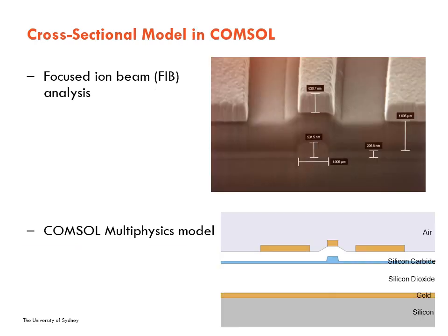For my research, I optimized the cross-sectional geometry of the electro-optic modulator fabricated earlier this year. Geometric measurements were taken using focused ion beam analysis shown above. I modeled this cross-section using COMSOL Multiphysics shown below, and analyzed its performance using the finite element method. Modal analysis allowed the group velocities and losses of the optical carrier, as well as the modulating RF waves, to be computed.